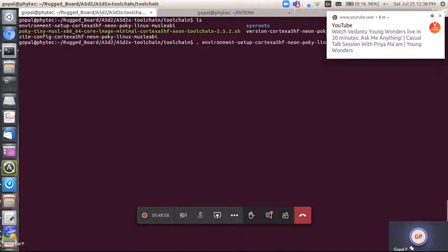I'm just changing the environment for this compilation toolchain. Here we have a board-specific compiler toolchain SDK. Those who have the board might get this SDK. Even our regular board community can straight away download this toolchain. Here I'm changing the environment from native to cross.